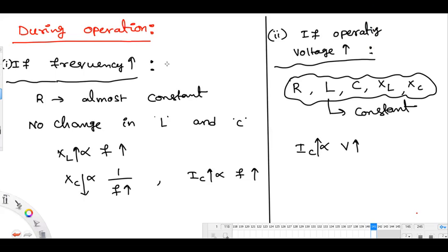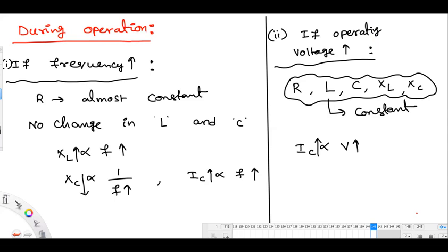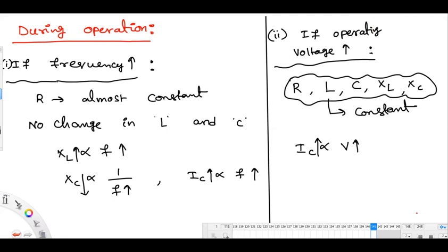As XC is very large in number, because we calculated some problem, you got kilo ohm. But how many kilometers? For 180 kilometers only you got kilo ohm. So for 1 kilometer, it will come in mega ohm. So in that perspective, the shunt current may be very less. But if the length of line is very high, shunt current is appreciable with respect to load current. Then we have to take it into the circuit. Just by looking at the number, I can't decide if it is low or high if I don't have another number to compare.